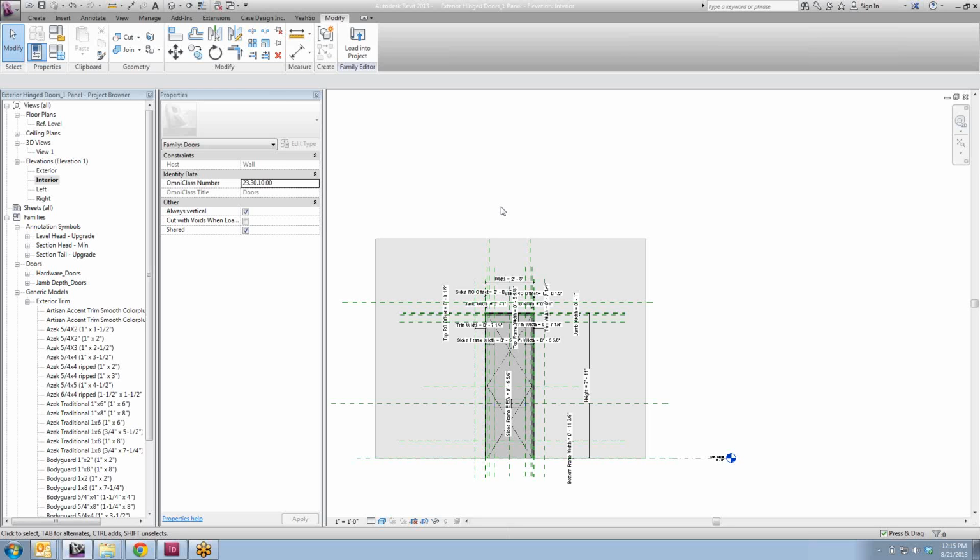So basically what I'm doing is making the door slab justified to one side of the wall depending upon the swing of the door and how you place it, so that it actually looks exactly the way it's built. You know what I'm saying? So the floor pin, and that actually helps with the look of the trim in plan also. Does that answer your question?